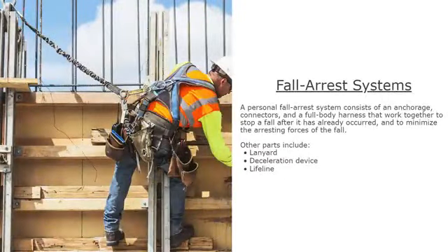And I'll get your attention right here. People don't do it. They're going to do a curtain wall, right? They got 4-foot rebar stubbed out. They didn't add it in. You can go on the internet and look at it. It goes in right about the thigh and comes out right about the armpit. You know how they get you to the hospital? They cut the rebar.